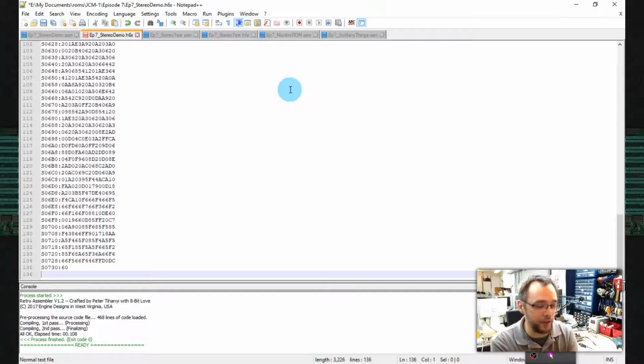Now there's one last thing I have to do. This is a plain text file in MS-DOS format. So it's like carriage return line feed at the end of every single one of these. You can't see them because I'm not showing it in binary mode, but basically every single one of those lines ends as a carriage return and a line feed. However, my monitor doesn't know how to deal with line feeds. I haven't programmed it to deal with line feeds because when you're typing into the console, you're never hitting a line feed button, you're hitting the enter key to tell it I'm done with this command. The enter key is a single character, it's carriage return. So I have to strip all these line feeds out of this.